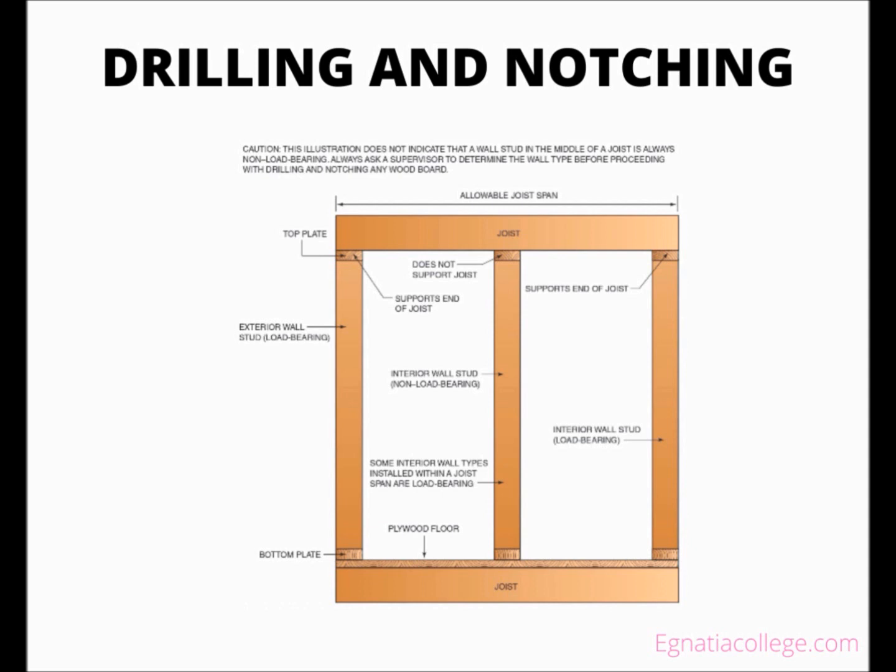The depth of the cut is strictly regulated and is determined by the area of the joist being notched. Holes and notches that place the outside diameter of a pipe close to the edge of a stud, joist, or plate must be protected against nails and screws. Most codes require that a nail plate, or stud guard, be installed wherever a 1½ inch nail or screw could penetrate the piping. A nail plate is a 1/16 inch thick steel plate that is available in different lengths and widths.